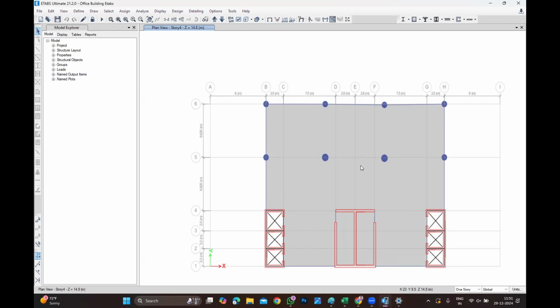This oscillation is going to stop because of this. Wherever the stiffness is huge, it tries to stop this acceleration, and it tries to stop what we call the drift, to control the drift. If there is a lack of stiffness, then it goes beyond. It is simple, the concept, don't try to confuse.